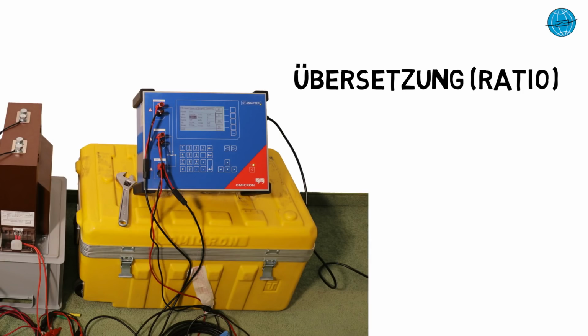Also with a CT Analyzer, we can test with an unchanged test wiring and we start the test. The CTA starts immediately and automatically with the determination of the ratio by previously independently determining the knee point voltage, and from this determines a suitable value for the test voltage.